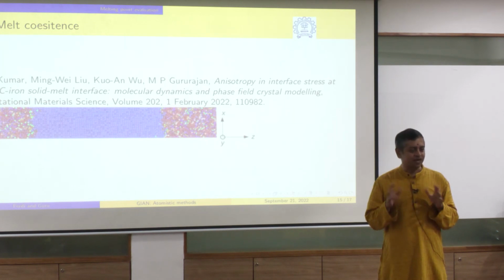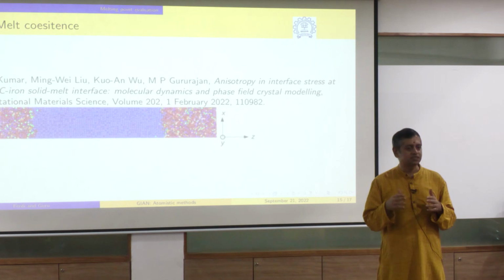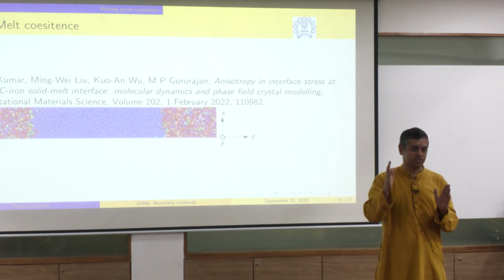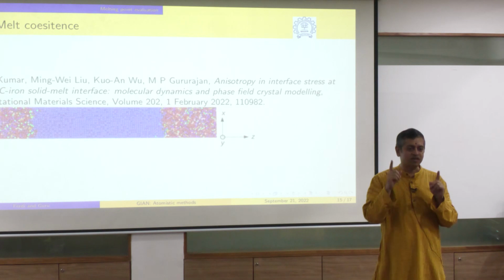The simplest way you can understand is that when the solid is getting molten into a liquid, the bonds are breaking, but the solid already has broken bonds at the surface. So melting will always start at the surface. So melting does not need nucleation, which is probably what you meant by the ordered structure that has to form. So there is a nucleation barrier in the other direction. So there is always a hysteresis,